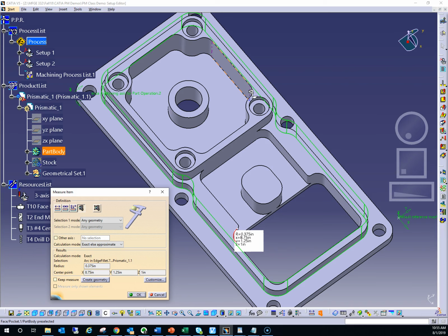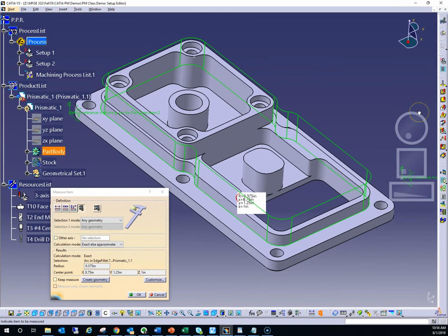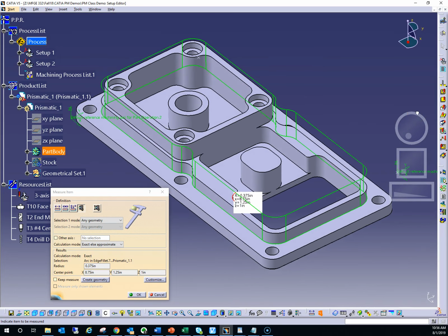Typically, we try to move the cutter to the corner without a dead stop, meaning that we'd probably want to use a cutter that has a smaller diameter. So in this case, maybe a 1/2-inch cutter would be appropriate. So again, that's the type of information that you want to start getting at, because that's going to figure into your planning for the tools you're going to use.